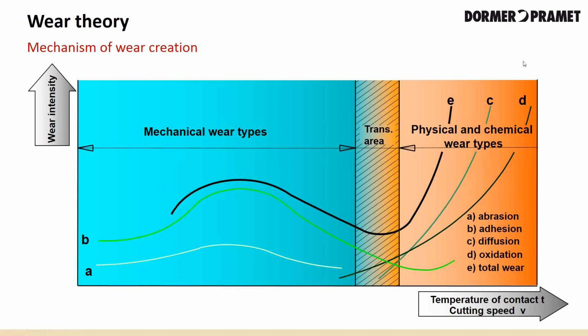As you can see, under the wear mechanisms, A and B fall in one area, and then you have C, D, and E on the right-hand side. It's indicative that as you go towards the right, the cutting temperature increases, allowing for different types of tool wear. And on the left-hand side, the blue area is the cooler temperatures, or as stated, the mechanical portions of it.